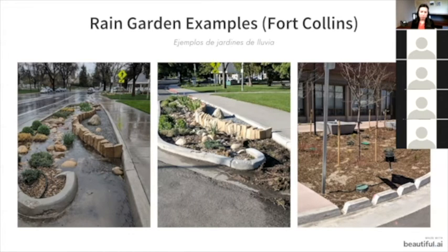So it's a form of controlling speed too. Then this is another picture after a rain event, the same rain garden, but it shows you why maintaining it is important. During a rain event, a lot of debris washed into this rain garden and has clogged the inlet. By clogging the inlet, water cannot get into your rain garden. So you need to note when there are these huge rain events happening and be sure to go and maintain your rain garden.